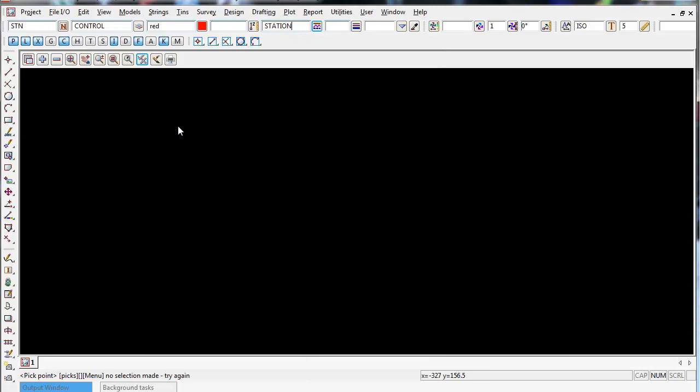Now once you have the CAD control bar set, we're simply going to enter the control coordinates by using the left-hand toolbars. I'm simply going to go up to CAD points, hold the left mouse button down, and step out one to create point. Release the left mouse button now. If you look at the very bottom left of the screen, 12D is prompting you to pick a position. You can simply left click anywhere on the screen, but since we're going to give these control points a defined coordinate, I'm going to type them in manually.